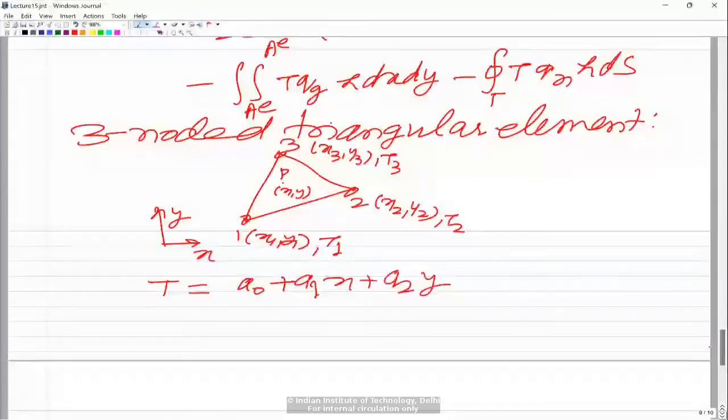And since t is a primary variable, we have to have that as degrees of freedom at the node, so that when we have a common node between different elements, we can have the same degree of freedom at each node, and therefore at the nodes the continuity can be enforced. And for the triangular element, at any common edge, this variation will give you the continuity of the temperature, so it would satisfy the inter-element compatibility. Let me put a superscript here because this is for one particular element. So yeah, that is what we do.